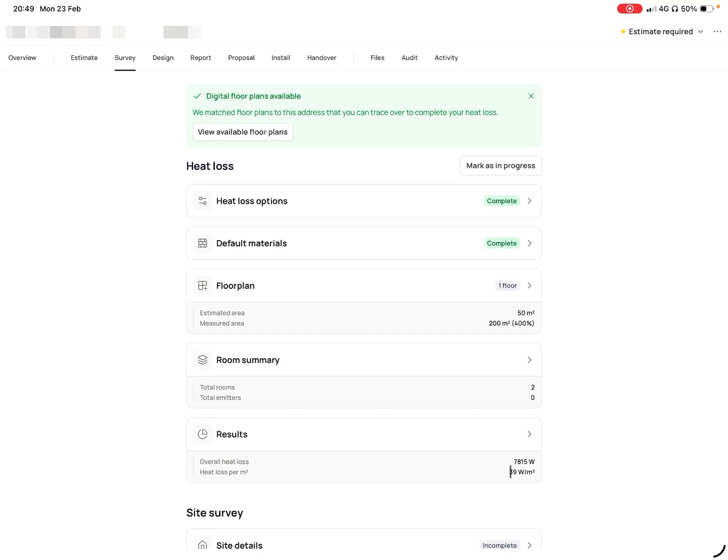And if you have a property where your heat loss figure done with this older method puts you into what's called a twin fan category, you may end up having it suggested to you that you have a heat pump that has two fans stacked on top of each other. And in some cases, that'll mean you can't have it installed at all in your property because you may have nowhere available for a twin fan unit to go.